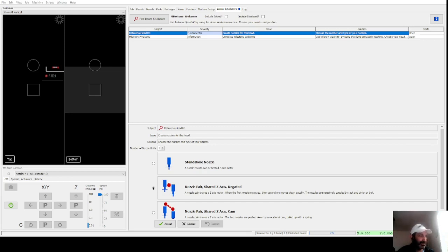So let's start out. We've chosen the nozzle pair, as I said earlier. The Opulo LumenPnP is a pair of nozzles, left and right. Well, at least it is in version 3.0, LumenPnP version 3.0. Left and right, driven by a gear or a belt, doesn't matter. Interestingly, they chose a homing position which is different than OpenPnP strongly suggests, and more to the point, they chose that